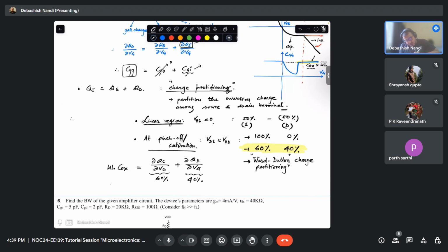Okay, so your CGS will be 2 over 3 WLCox, and your CGD will be 1 over 3 WLCox.